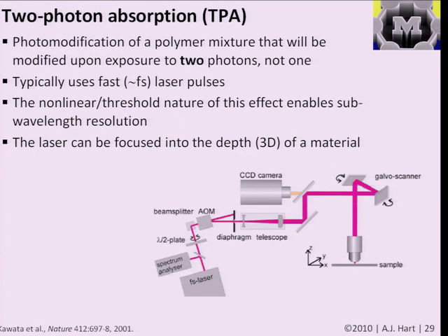So as I said before, one of the limitations of these planar processes is that it's difficult to make 3D structures, or it takes a long time to make 3D structures, no matter how you look at it. And there's also some geometric restrictions. So for example, if you use lithography to build up different films, it's easy, it's straightforward to do something that, say, is a pyramid, but it's less straightforward, because you need the beam access or the imprint access, to do something that, say, has a reentrant structure like this.